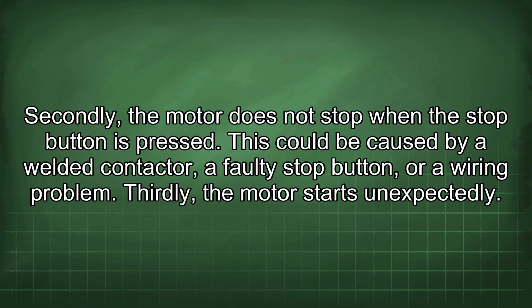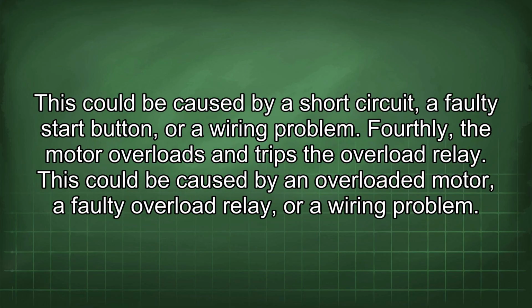Thirdly, the motor starts unexpectedly. This could be caused by a short circuit, a faulty start button, or a wiring problem. Fourthly, the motor overloads and trips the overload relay. This could be caused by an overloaded motor, a faulty overload relay, or a wiring problem.